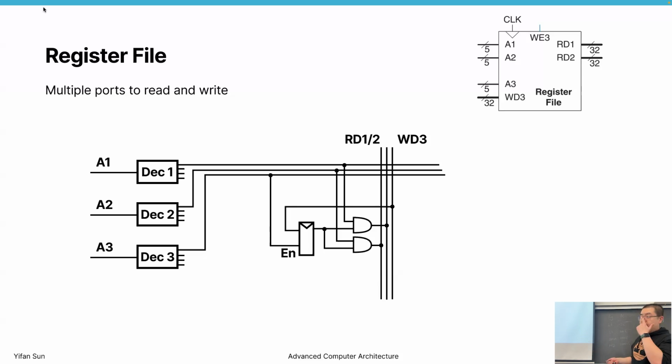Okay, so almost the 3 independent input and output logic. And when this one is generating data, then we go through some gate. So if this one is selected, then it goes onto this wire. And if this one is selected, it goes to this wire. So in theory here, we're basically using an AND gate to serve as a multiplexer to go to the read wire. Then on the write wire, it goes back to here. Then we don't have the loop back, just consider loop back is built into the register. Okay.